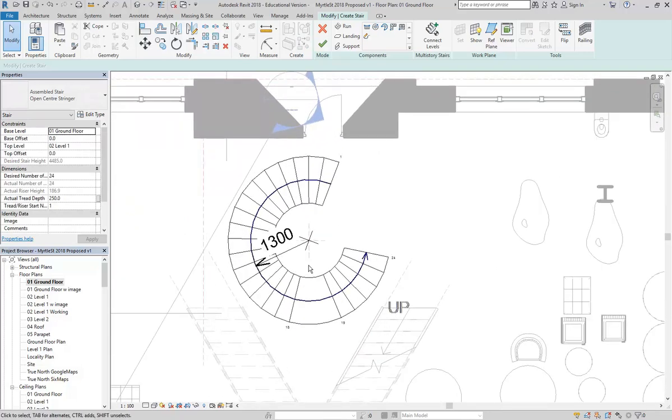It's also a problem in terms of construction because if you've got a curve that's a helix, which is what you get on the side of a spiral, it's not even a spiral at all. A spiral is a curve that changes radius. A helix is a curve that changes elevation as it curves. So the correct name for these stairs is a helical stair, but no one says that. So they're not spirals, but they're called that. A spiral stair will just leave you smaller.